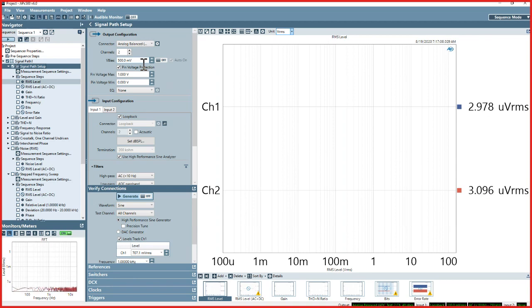Now, when you have auto range enabled, all of that is, so to speak, hidden. That is to say, the analyzer itself knows when it changes the output range and coordinates that with the input side. So no measurements are made during the range transition period. And the timing of that actually does vary, but it's generally measured in milliseconds.